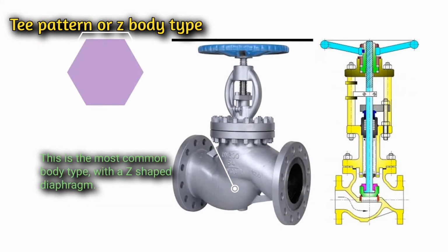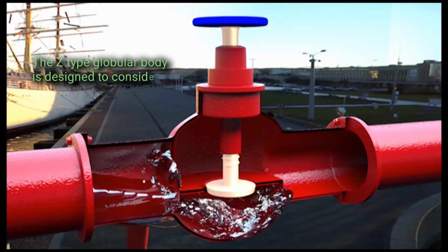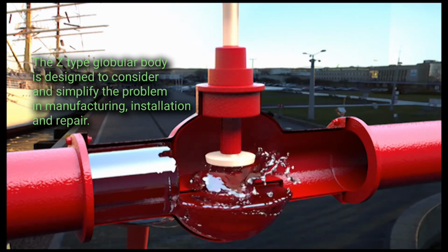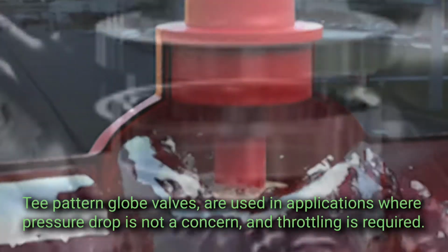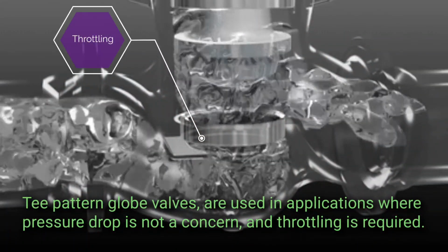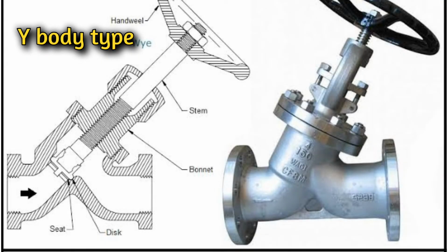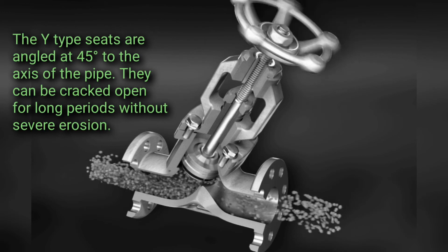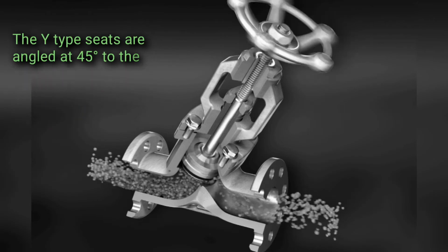T pattern or Z body type. This is the most common body type, with a Z-shaped diaphragm. The Z-type globe body is designed to simplify manufacturing, installation, and repair. T-pattern globe valves are used in applications where pressure drop is not a concern and throttling is required. Y body type. This is designed to solve the high pressure drop problem in Z-type valves. The Y-type seats are angled at 45 degrees to the axis of the pipe. They can be cracked open for long periods without severe erosion.